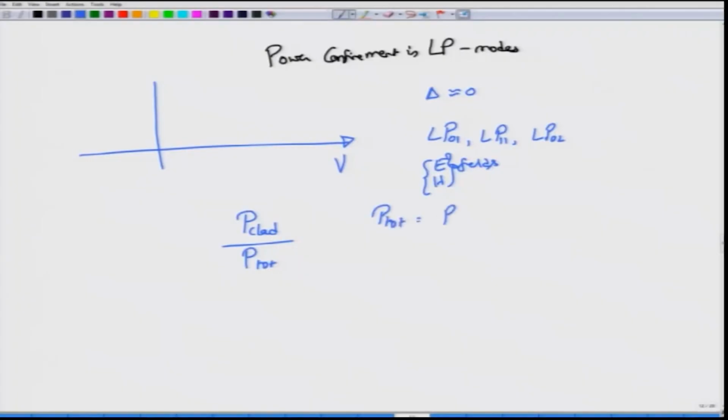So, the total power, assuming no losses or other things that we are going to talk about later on, is split between the core and the cladding. You want almost the power in the cladding to be equal to 0, because you do not want any power loss on top of whatever absorption losses the fiber material itself will present to you.